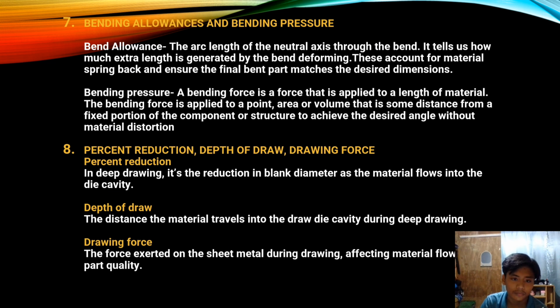Percentage reduction, depth of draw, drawing force. Percent reduction in deep drawing is the reduction in the blank diameter as the material flows into the die cavity. Depth of draw is the distance the material travels into the draw die cavity during deep drawing. Drawing force is the force exerted on the sheet metal during drawing, affecting material flow and part quality.